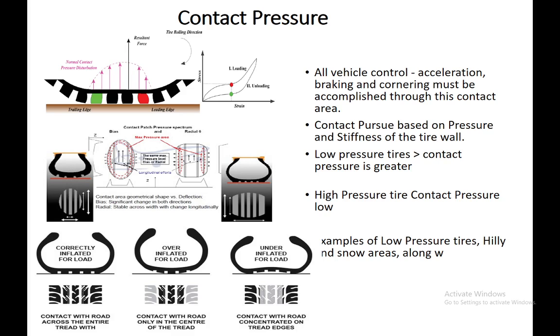So what is contact pressure? Contact pressure is when stresses are developed due to the wheel load on the tire imprint area of the pavement surface. We usually have pressure on the contact between the vehicle tire and road pavement, which is very important to determine in terms of load intensity. A uniform circular vertical contact stress is commonly assumed as the contact pressure, where contact pressure is equal to load divided by area, which we call F by A.